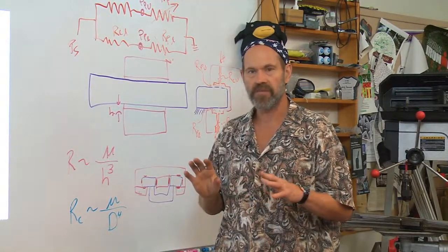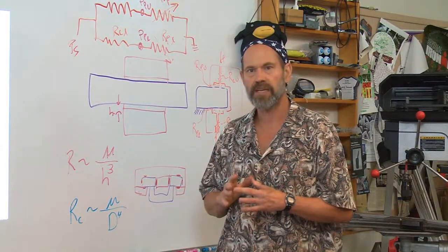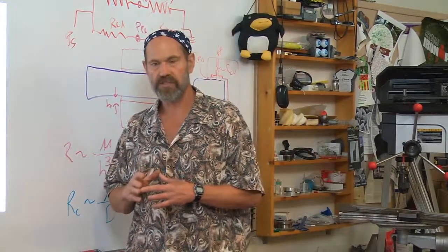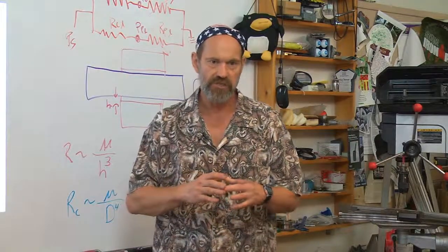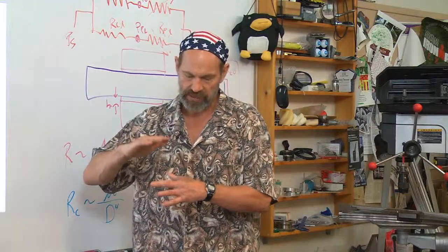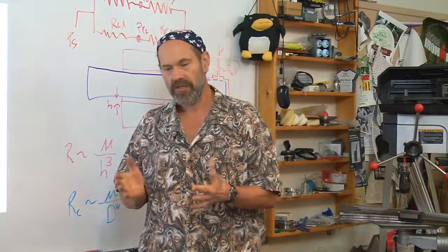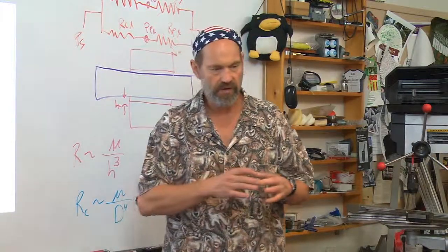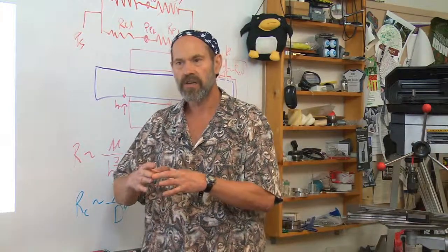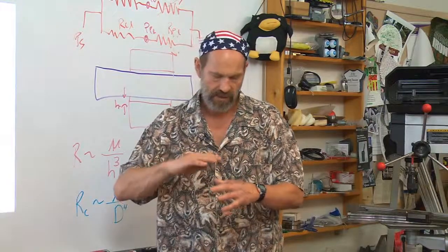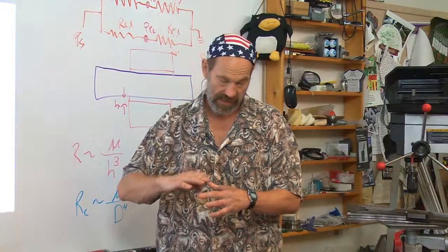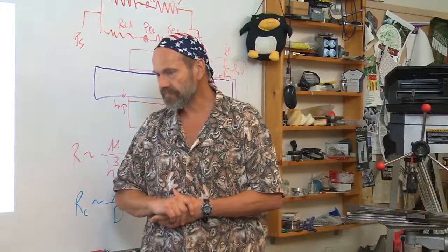Well, that happens in some of the most sophisticated machines on the planet, known as wafer steppers, where wafer steppers are those devices used to transport silicon wafers under lenses so that you could print the pattern of the integrated circuit onto the silicon. The stages, those are the devices that carry the silicon wafers at very high speed, very high precision around under the lens stack so that the individual silicon die can have their circuits printed on them.